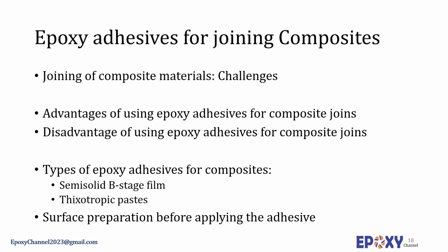Recommended surface preparation of many composites simply consists of a solvent wipe to remove dirt, followed by a mechanical abrasion. The abrasion degree is important and it is desired to be set to a level where the glaze of the resin surface is removed but the reinforcing fibers are not exposed. Many surface abrasion methods can be applied to composite parts, including light sanding, grit honing, vapor honing, and other methods.